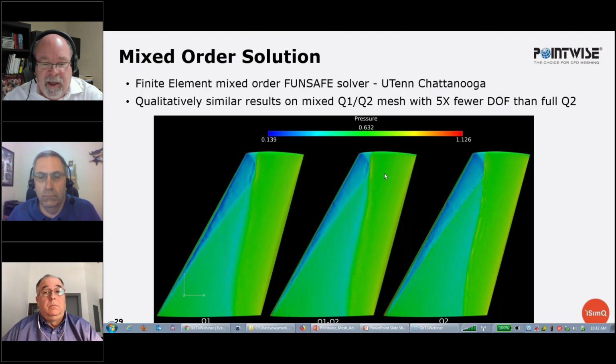So a key enabler for this, for computational efficiency, is the solver must be able to interpolate an incoming initial condition field from one mesh onto the new mesh. And if that's done robustly and smoothly and efficiently, that really is enabling in terms of CPU time. The process has to be robust inside that solver. It's got to happen with no user intervention. This has to be implemented in an automated loop. Doing it by hand would be fairly painful to start and stop these components. You want it to happen automated, and prerequisite is that the solver runs with no intervention.